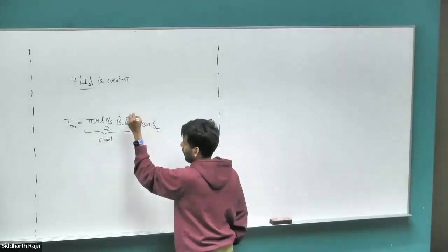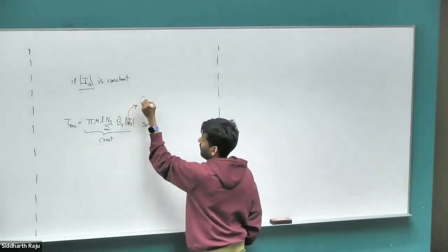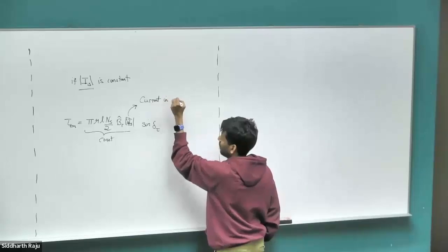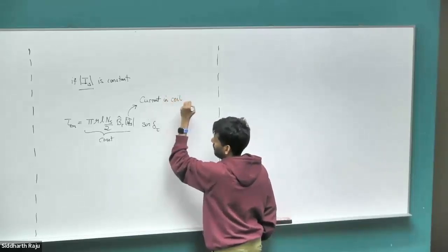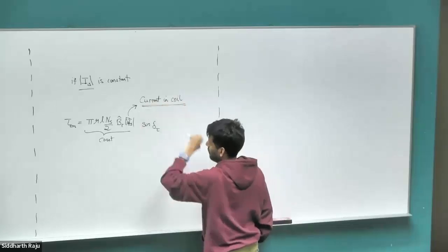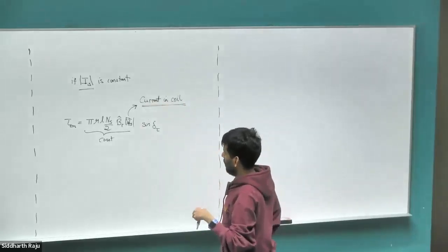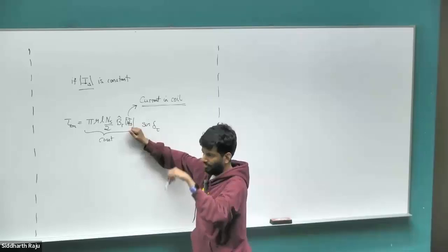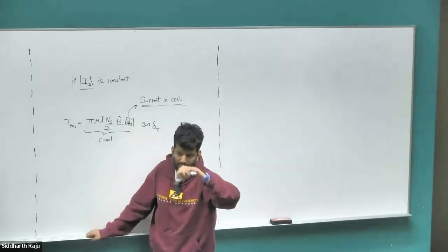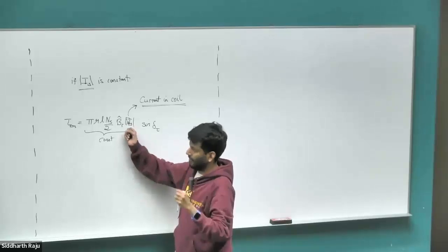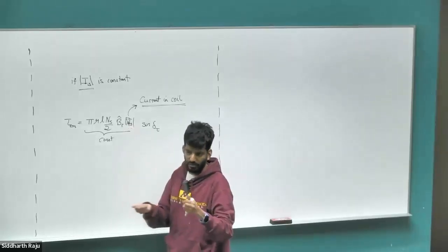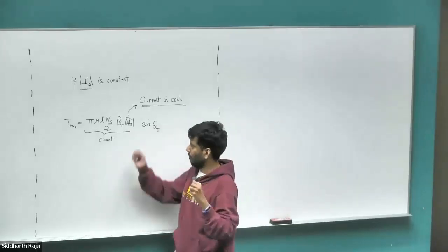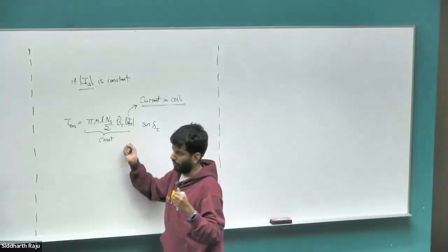So the stator current, you should be quite careful. This is the coil and the current in the coil. For a two-phase motor, the two-pole motor, it doesn't matter. Current in the coil is same as the current in the terminal. But when we go to polyphase, when I model it, I'll make this more clear what the term is. We have already done this in the previous lecture, but I'll go over it again once more when we model the motor. But this is the current going in each of the coils. So if you have 6-pole pairs and the 3 coils are connected in parallel, then this would be the terminal current divided by 3, because the current would branch into all of those 3 coils equally. So it will be a factor of 3 divided. But if those 3 coils are connected in series, then the terminal current coming into the motor is same as the current in each of the coils. Right? Then there will be no division factor.